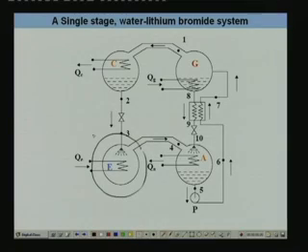Let me explain how this is done with suitable equations. I will just give an example. For example, let us take the evaporator. If you are applying mass balance to the evaporator, remember that the cooling water, chilled water and so on do not come into the picture, because we are not considering how we are supplying or rejecting heat. For our analysis we are concentrating only on the refrigerant side, inside the system. It is steady flow, so whatever mass is entering must go out, that means m dot 3 should be equal to m dot 4. This is the mass balance. And what is the energy balance?